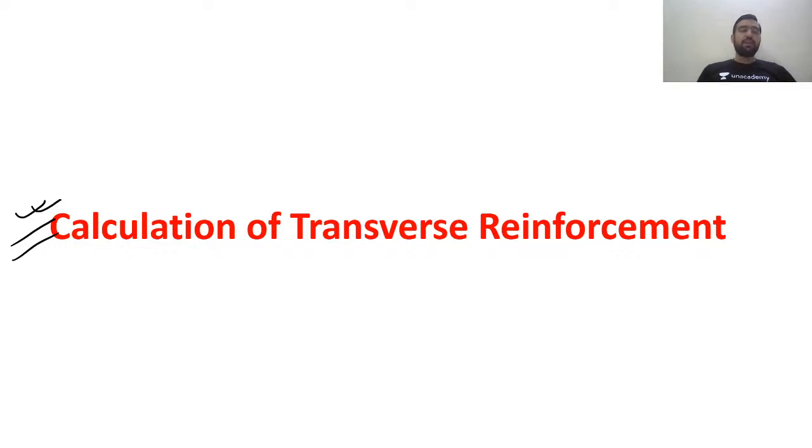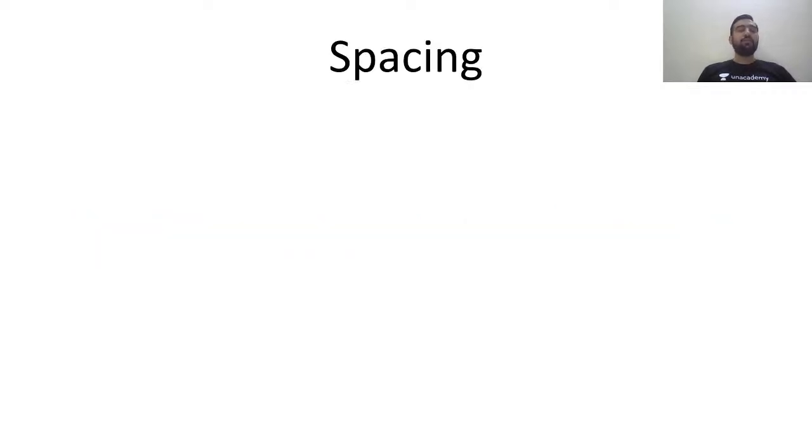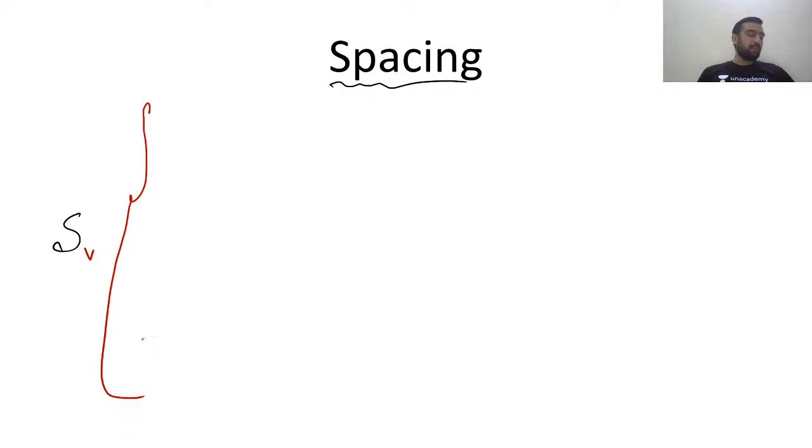So here as well, the Indian Standard 456-2000 has given special provisions to find the spacing of the vertical stirrups or inclined stirrups. So what are the various formulas? I think I have written this. Today we are going to use all such things, so I am writing each and everything at a single place. First one was 0.87 fy Asv. I hope it is visible to you guys.